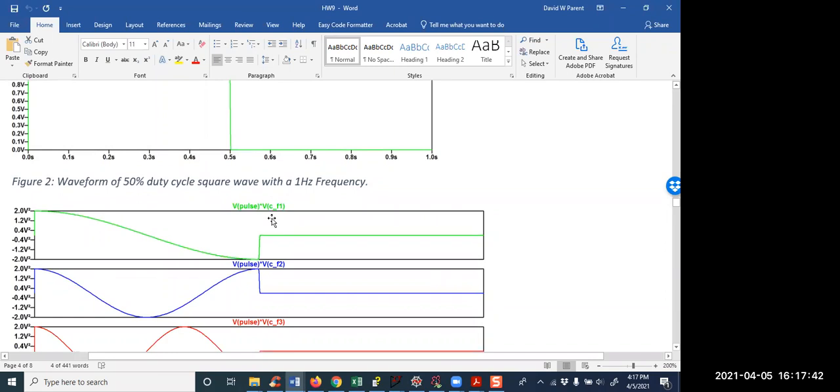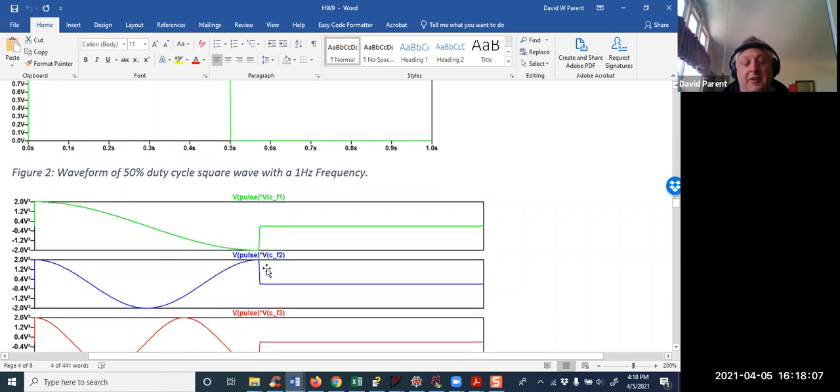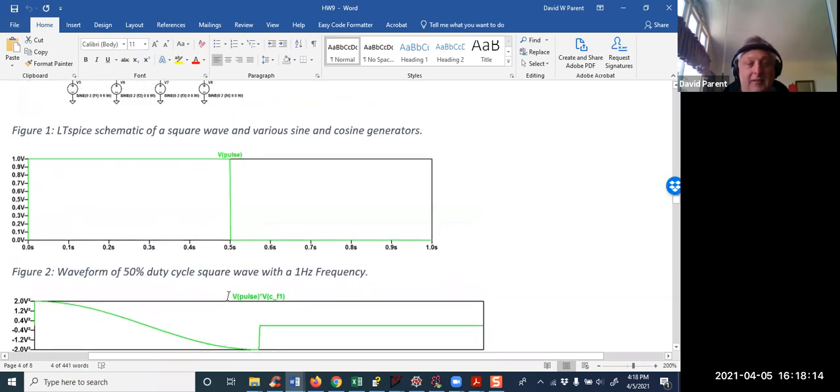You find twice the average of the signal times a cosine wave at the fundamental frequency. How do you find A2? You find twice the average of the signal times a cosine with twice the fundamental frequency. What about 3? 3 times the fundamental frequency, right?